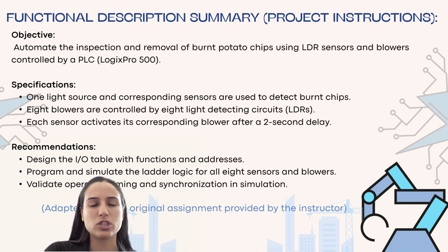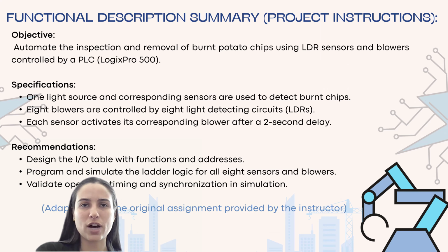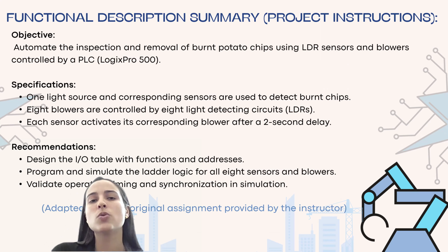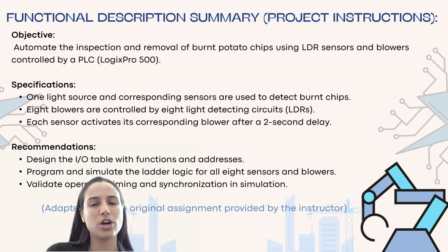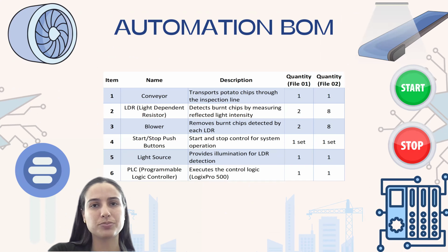The recommendations provided by the professor are to create an input-output table with their functions and addresses, the program, and simulate the ladder logic for all 8 sensor blowers. I'll be presenting the first file and the second file. The first file is with 2 blowers and 2 LDRs, while the second file will be 8 LDRs and 8 blowers.